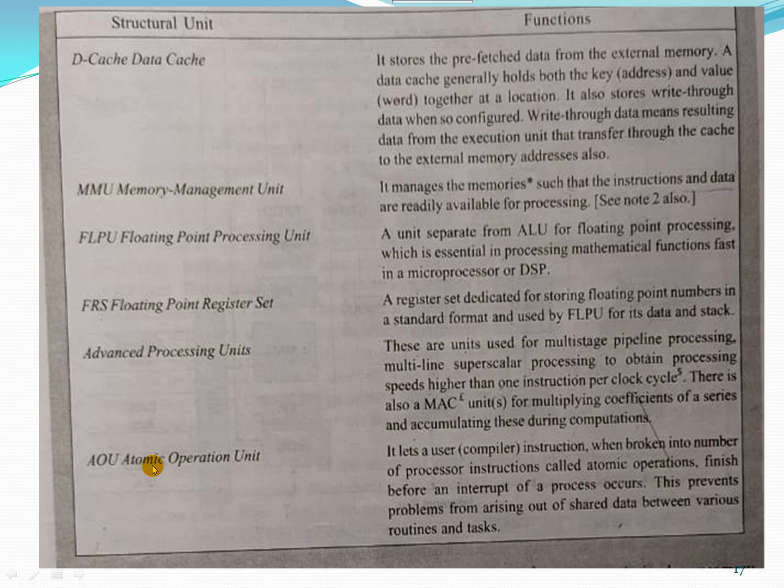Whenever we are dealing with a particular program, we will be having some variables in it. Those variables may be shared data which may get changed in the due course of the program. So a particular variable may be changed at any time, so that the processing will be affected by the changing of the variables. Those kinds of problems are called shared data problems. Those problems can be avoided by using these atomic processing units.